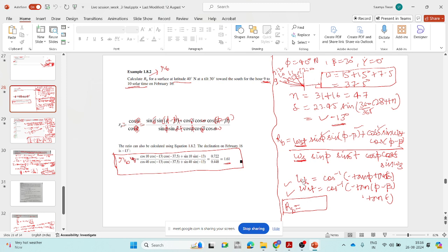But if I'm going to calculate it for the whole day, then here comes this formula omega s for a horizontal surface, and omega st for your tilted surface, where beta, that tilt angle, will be included, and then you get this omega st and put it into the equation. I hope you got the difference between both these things.